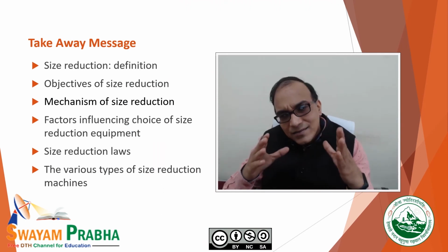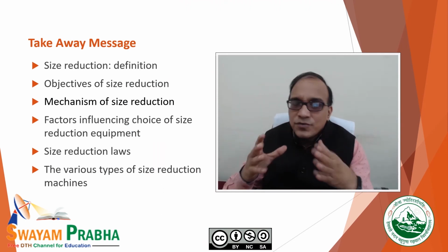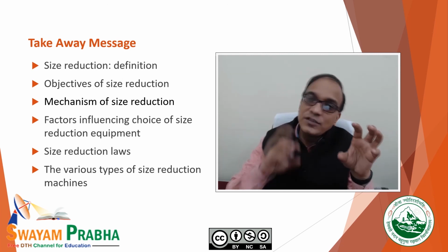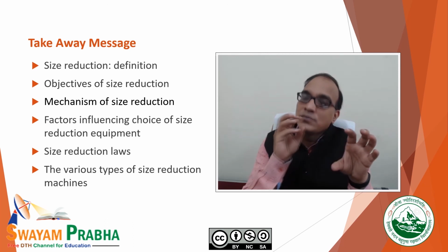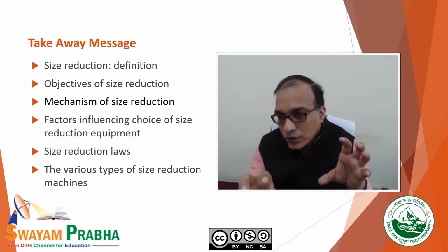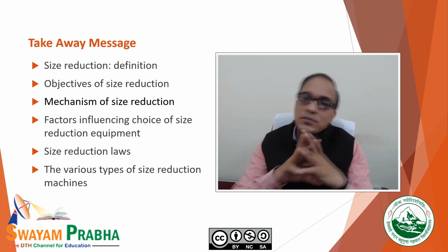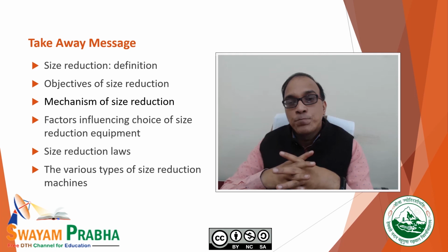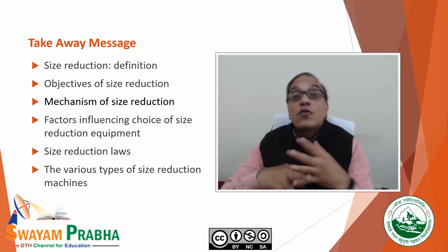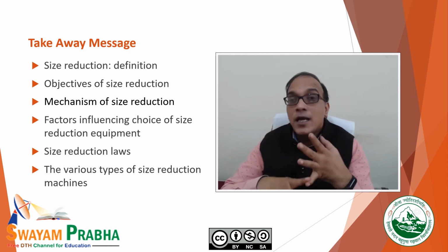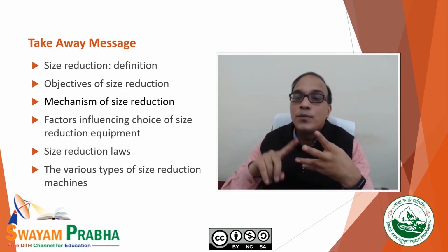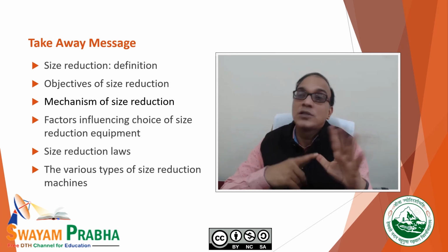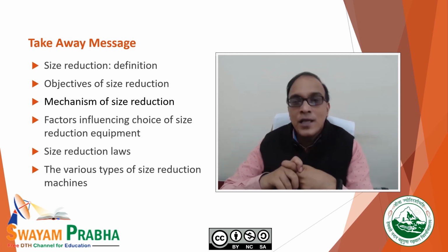What is the takeaway message we can have? Size reduction: bigger particles, with the help of energy, can be broken into smaller particles of uniform size as per the requirement. Size reduction is needed for improving the surface area, solubility, flow property, mixing, dissolution and absorption.